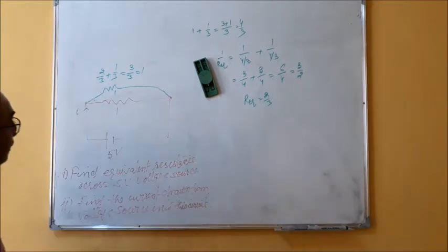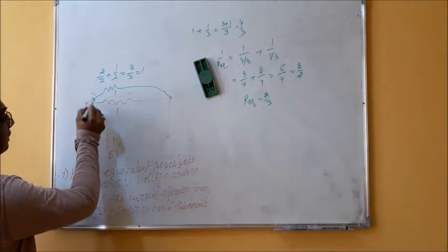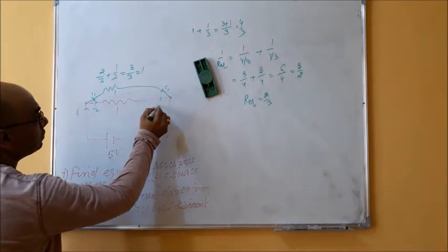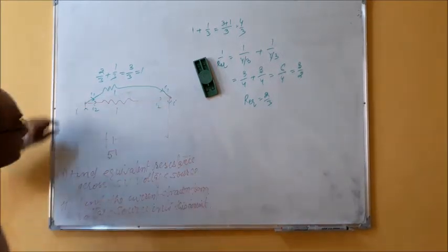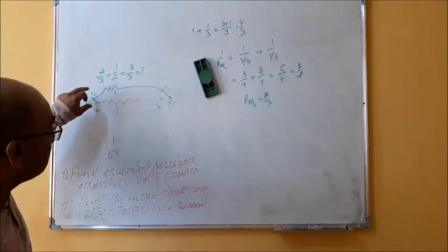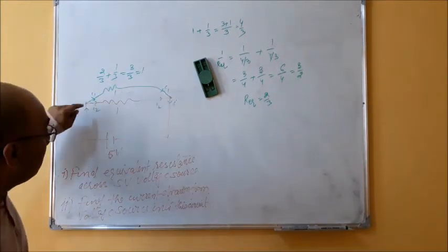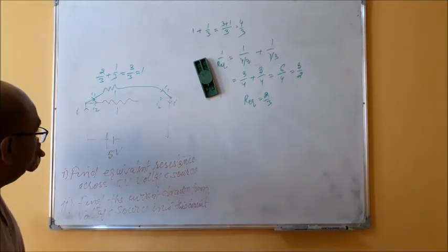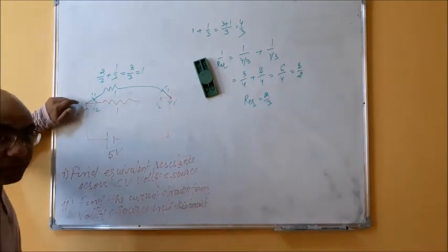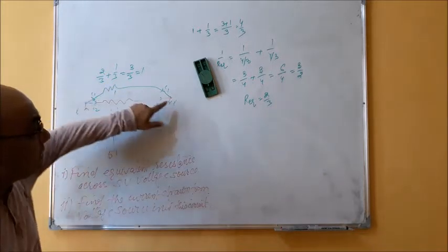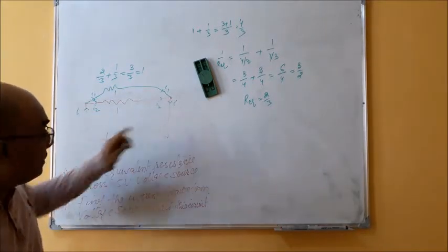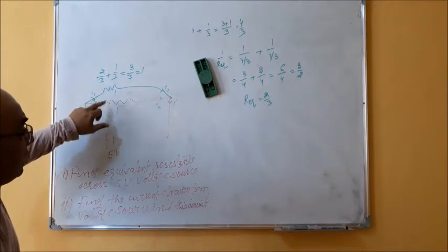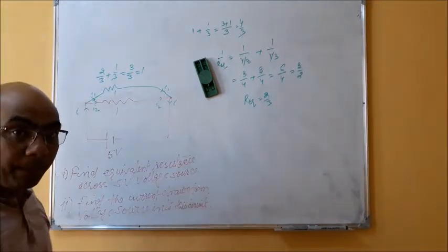Now again you see, I1 is going there, I2 is going there, at this point I1, I2, so they make I. This means in this circuit, which has the two resistances 1 and 1, if current is distributing at this point, the same current is coming out which is coming in from this point, and hence we can say 1 and 1 again are in parallel.